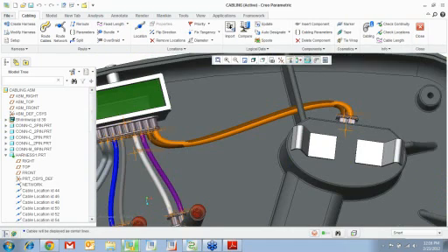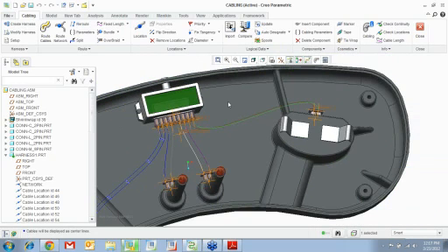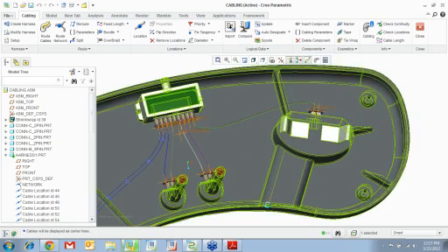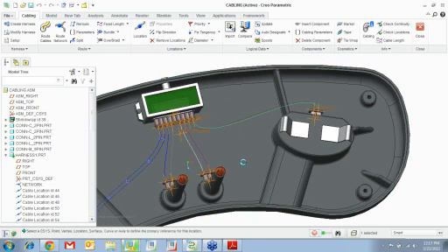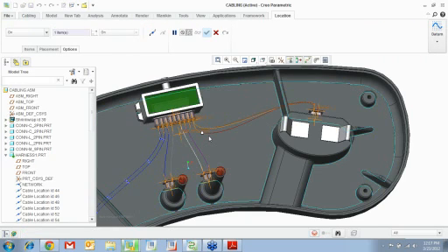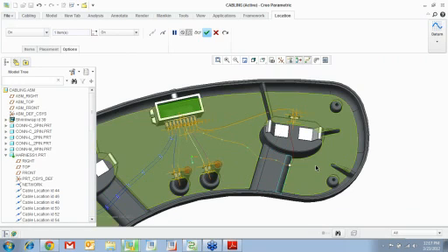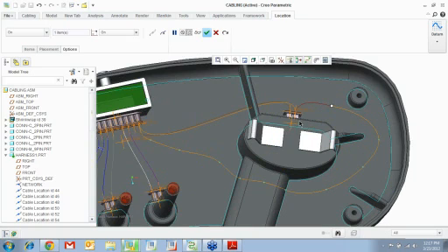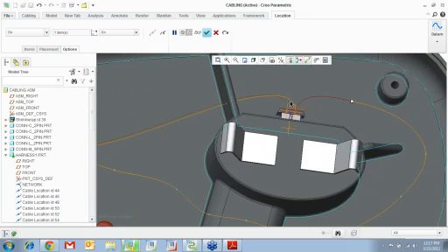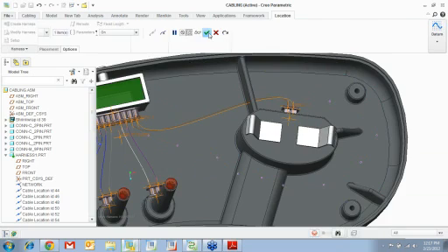So you go select both of them, right click, you just get this. So here you go, insert location, and you want to start off 1, 2, 3, and you can see how your cable kind of follows your location path. Right? So there you have your locations, and you can say done. Now we do the same thing for this.